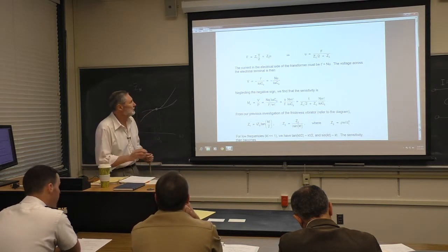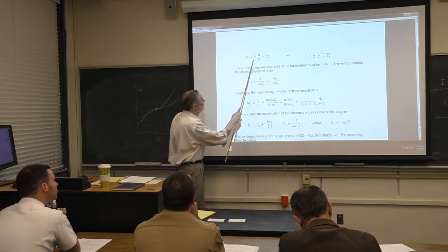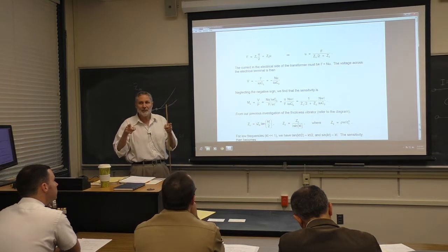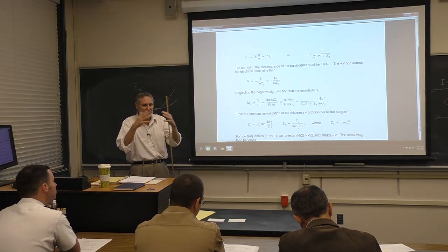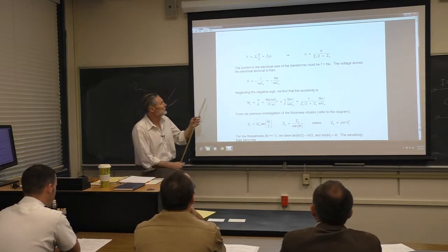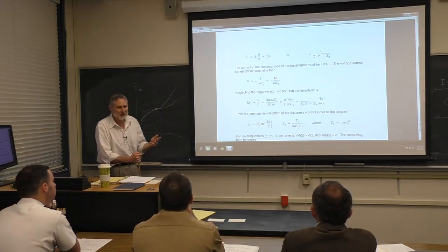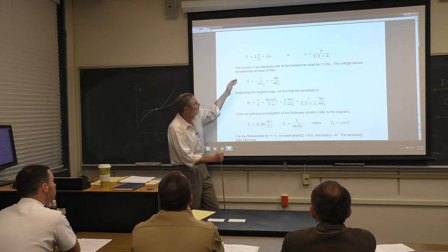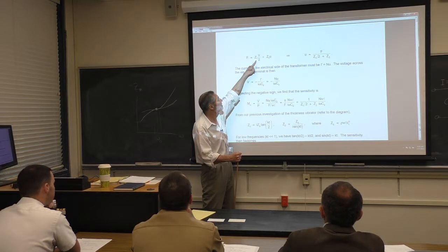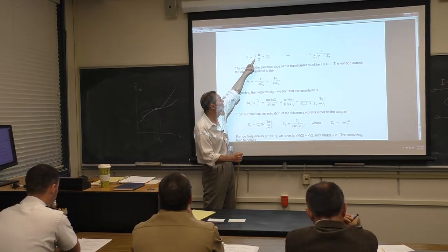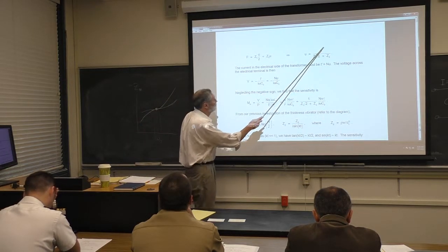Okay, so if you look back at that circuit, I think it's better to move this 1/2 out here. We have these two Z1 impedances in parallel. We're now combining the two loops, just thinking of it as one loop. We've got this total current U here, U1 plus U2. The two Z1 impedances are in parallel, so they add in reciprocal, and we're going to get 1/2 the impedance here. I think it's better to think of it in terms of that, and then we have that. So this allows us to solve for the velocity in terms of the force.